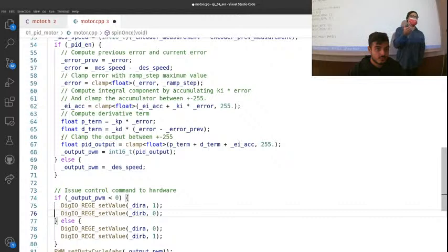So if you want to implement the ramp, the ramp means, given the actual PWM control and the desired PWM control that you want to reach, that will be the height of your step. But instead of reaching it immediately, you reach it by increments that are at most a maximum that you define. So you are defining the slope of this ramp. At each time, you ask, where do I want to reach? Should I go up or down? Up. Okay, if you should go up, then increase the actual PWM bit by bit until you reach the value that you want. And so you have this smooth effect.